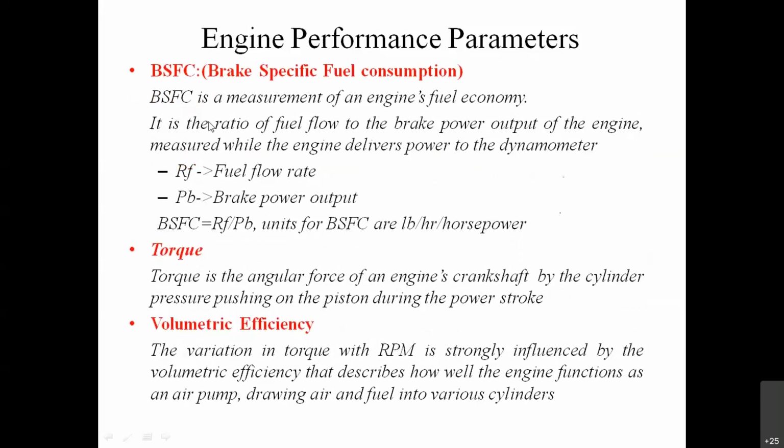Apart from that, there is one more term which is known as brake specific fuel consumption. It is simply the ratio of fuel flow rate to the brake power output. It is a measurement of the engine's fuel economy, how much fuel will be utilized for various speed and load values. Torque is the angular force of the engine's crankshaft with the cylinder pressure pushing on the piston. Basically, it's the force which is responsible for rotating your crankshaft. That is known as your torque.